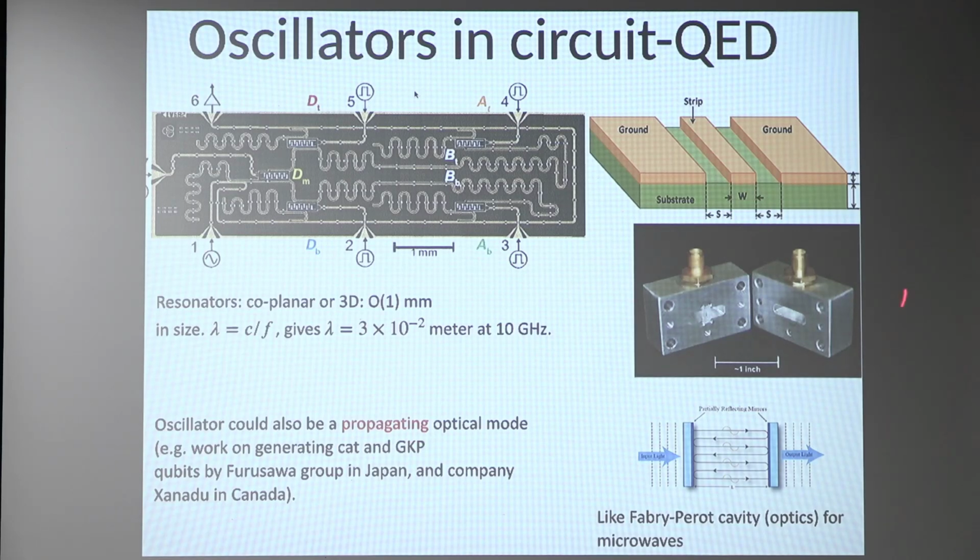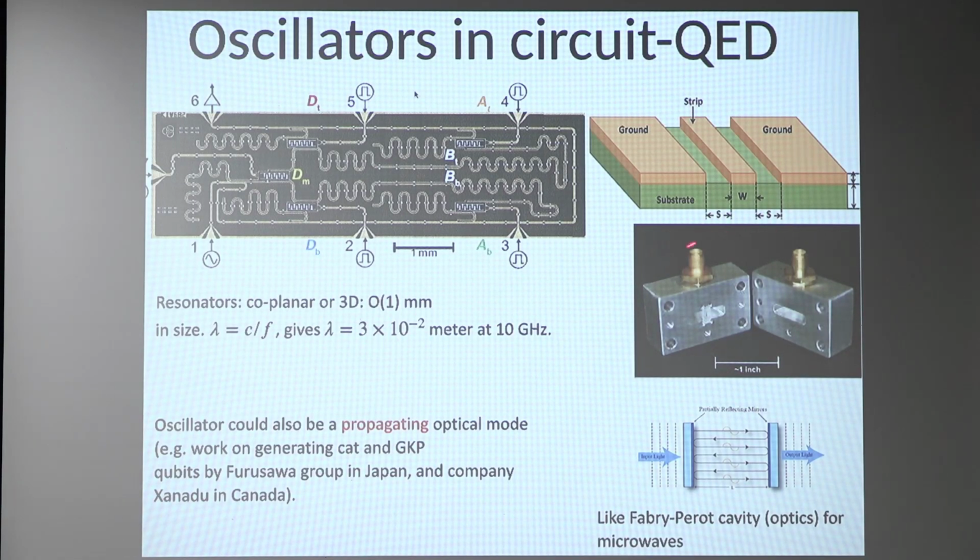Okay, but now another setup, in which quite a few experiments by the Yale group have been done, is to use 3D cavities. In the 3D cavity, you really have something like a block of aluminum. There's a hollow in there. This is like some coax cable that goes in there. And there can be an electric field in this hollow. And so there are resonant modes that you can address. And you'll see another picture of this as well.